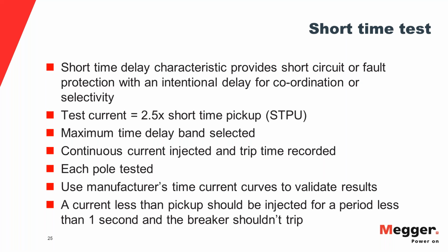In addition, a current less than the pickup needs to be injected for a period less than 1 second, and it should be verified that the breaker doesn't trip at that current.